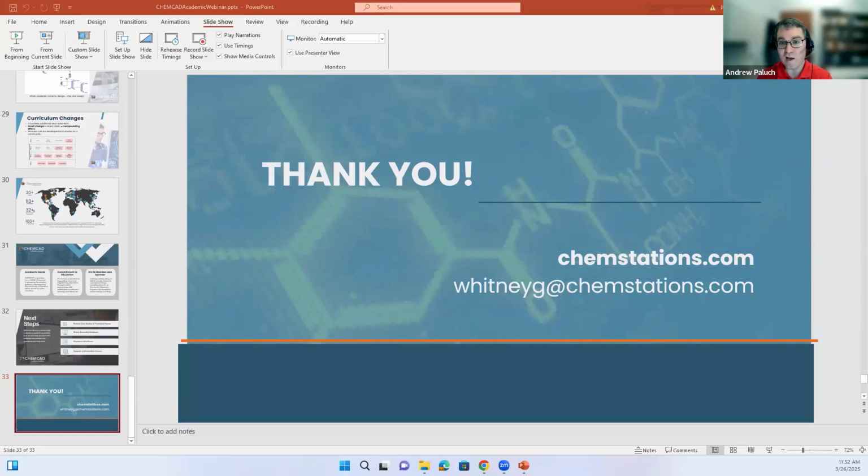So the answer is yes, but for a specific case like that, ChemCAD's not going to have internal built-in data, so that's something you would need to have and then implement within the model. And it's not overly difficult. If you have equilibrium data, the manual will take you through the form of the equilibrium expressions that ChemCAD uses, and even how to convert between different forms or units to be able to implement within modeling that unit. And the same thing with kinetic data as well.